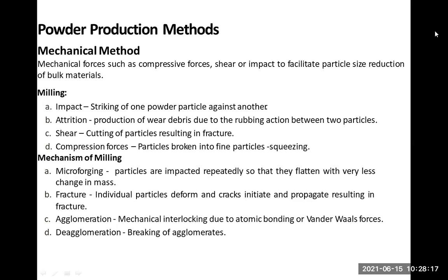In case of milling, we are going to consider impact, adhesion, shear, and compression force. In case of the mechanisms, what is going to be considered is microforging, fracture, agglomeration, and de-agglomeration. Regarding impact, striking of one powder particle against another is impact. Attrition is the production of wear debris due to the rubbing action between two particles. Shear is the cutting of particles resulting in fracture.